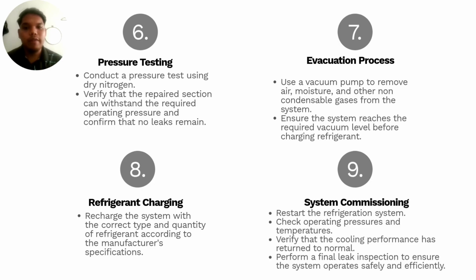The next step is refrigerant charging. The correct type and quantity of refrigerant are added according to the manufacturer's specification to restore normal system operation.